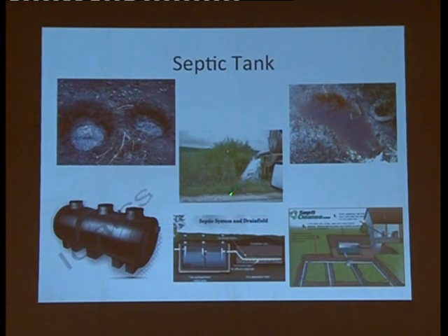Wherever they find some place where people are not watching, they go and discharge it, and it has millions and millions of pathogens and a high organic load, so that will be contaminating. And a septic tank, you know, acts only as a settling tank with a little bit of digestion. The water coming out of the septic tank will have very high pathogen concentration and organic matter. So we should have a proper soil treatment system. This is the basic concept of any septic tank design.